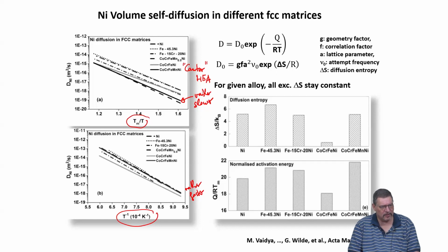Then a variation at constant homologous temperature, or also even at constant temperature, by 1 order of magnitude is not unexpected, because you have disordered FCC lattice contributions. So whenever you add a new constituent, there is bound to be lattice distortion. There is bound to be different ways the elements interact with the vacancies. Here we always have substitutional diffusion mechanisms working, so vacancies are important.